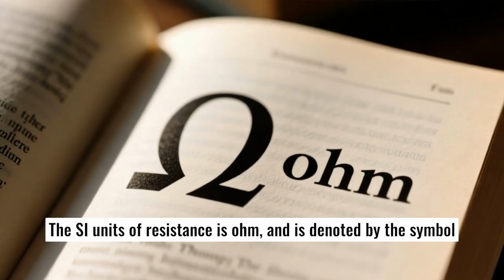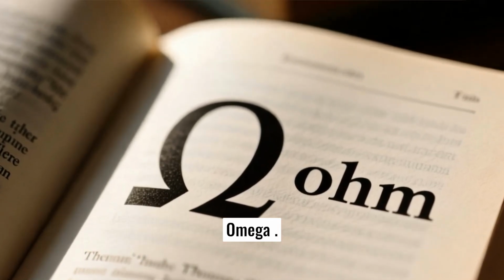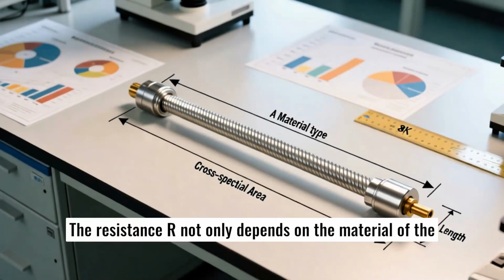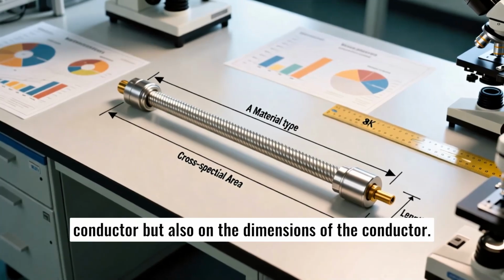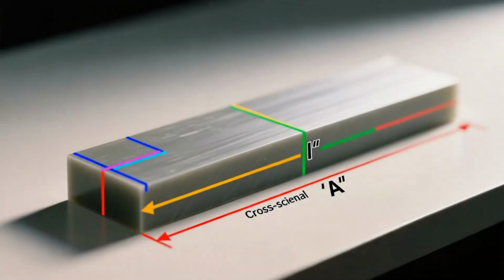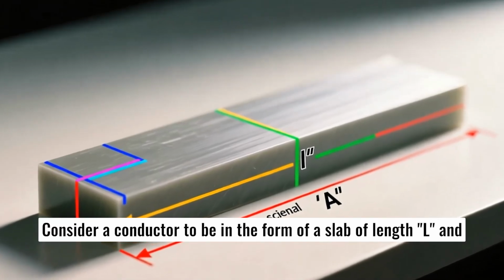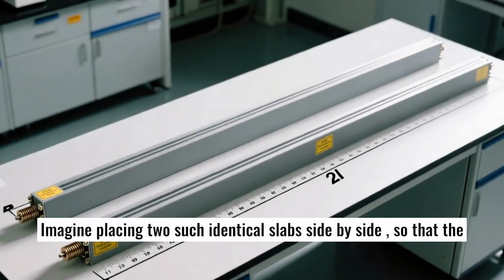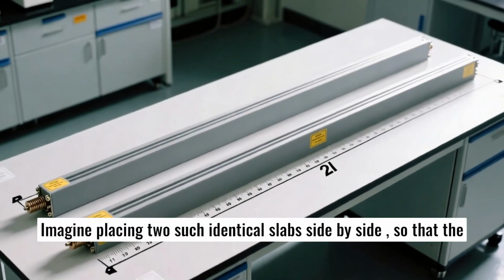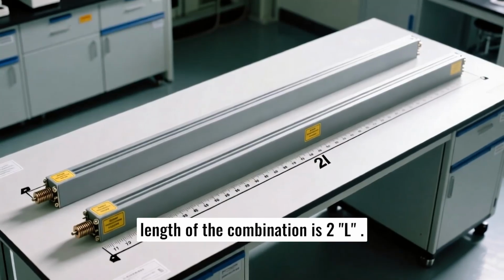The SI unit of resistance is ohm and is denoted by the symbol omega. The resistance R not only depends on the material of the conductor, but also on the dimensions of the conductor. Consider a conductor to be in the form of a slab of length L and cross-sectional area A. Imagine placing two such identical slabs side by side, so that the length of the combination is 2L.